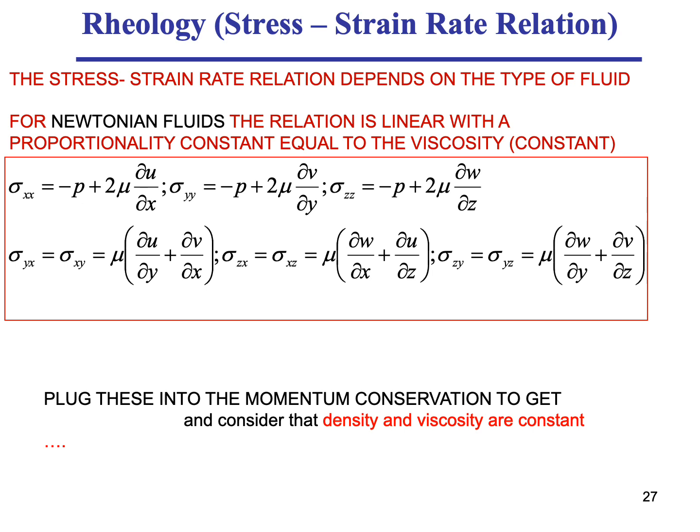We're familiar with the pressure term. The normal stress, as we talked about a minute ago: take the honey between your two fingers and try to pull the fingers away from each other. You move them at a certain velocity w in the z direction, and that's what we mean by a normal stress. We're not rubbing our fingers against each other, we're moving them away from each other and trying to pull the gum or the honey or the glue that's between our fingers. So that is the normal stress right over here.